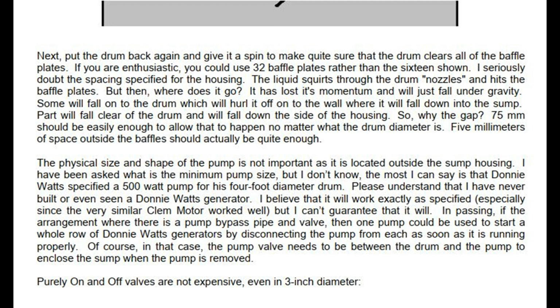The liquid squirts through the drum nozzles and hits the baffle plates. But then, where does it go? It has lost its momentum and will just fall under gravity. Some will fall onto the drum, which will hurl it off onto the wall, where it will fall down into the sump. Part will fall clear of the drum and will fall down the side of the housing. So, why the gap? 75 mm should be easily enough to allow that to happen no matter what the drum diameter is. 5 mm of space outside the baffles should actually be quite enough.